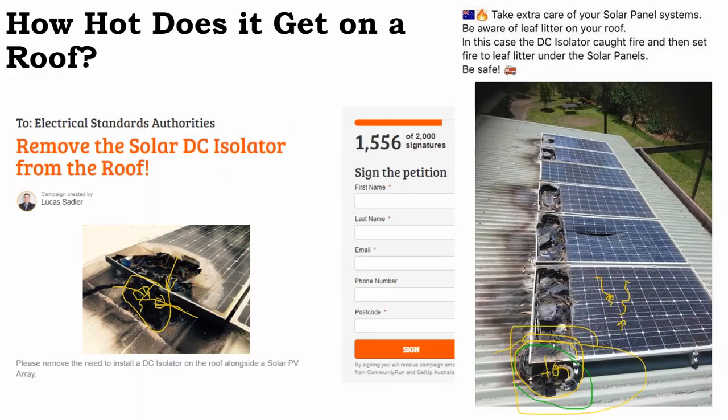So a terminal point where the cables come in and land on a metal bar gets hotter than the rest of the box. And so the problem becomes when you build a solar array, then you're like, oh, I need to have a box up on the rooftop. So you go to Home Depot and you buy a box and a terminal bar, and you're not using solar specialty parts, but you're just using stuff that they have at the supply house.